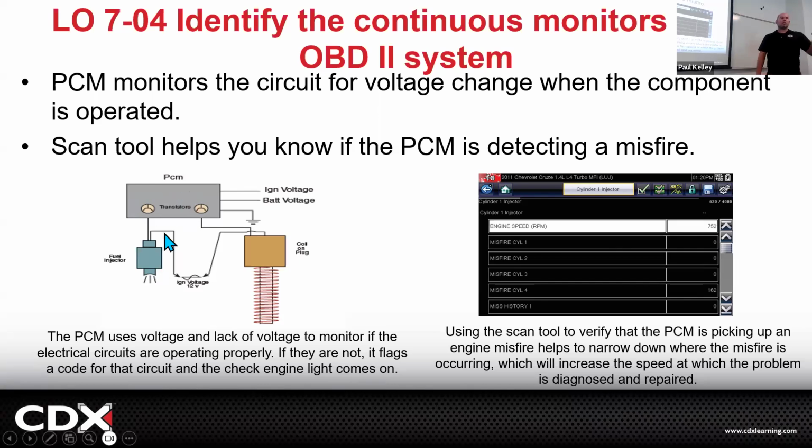Now, I'm not going to knock the OBD system. I think it's amazing because if we didn't have onboard diagnostics and this PCM wasn't monitoring its own voltages, where would you even start? The car would come in, and if the injector wire is chewed, what do you think the symptom is? Anybody think they can guess? If one injector wire gets chewed and that one injector goes to one cylinder and that one cylinder no longer gets fuel, yeah, misfire, shaking, misfiring.